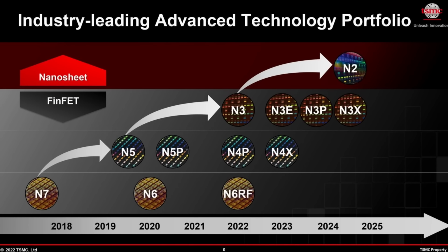Like every CPU, Intel's 386 also made heavy use of the NAND logic gate. Ken Shirriff went the extra mile and produced high-res die shots that allow us to take a look at real photos of the NAND standard cells inside the 386. As you can see, it's a CMOS-based standard cell, as it uses both NMOS and PMOS transistors. This specific combination of transistors is able to perform a NAND logic operation. That's why it's a NAND standard cell. But there's more. The Intel 386 also implemented much smaller and much larger NAND standard cells. All three cell types perform the same function, but they do so with different electrical characteristics.